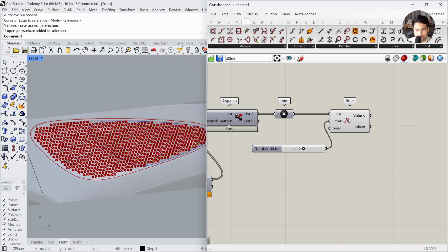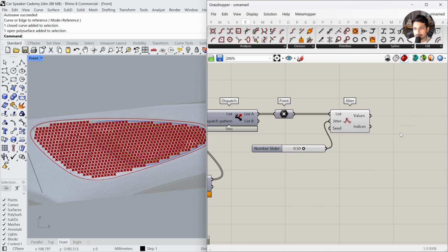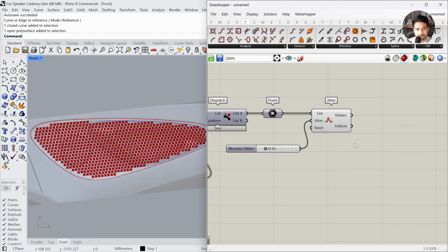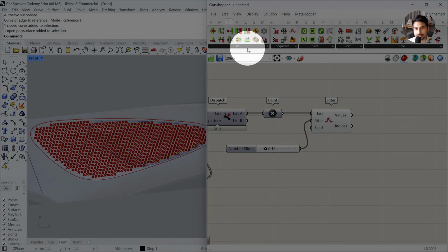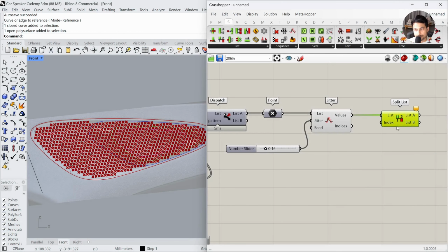Okay. You can read more about what this formula looks like by going to settings. But yeah, in our case, we will just set it to a lower number and fine tune it. Okay. Now it has just randomly shuffled. That doesn't isolate these points. So what we are going to do is that instead of these 745 points, we will select the first maybe 300 or 400 or 500 points. Okay, how? Let's go to sets, list, and we will split the list. Split the list of 745 points at maybe 400 index.